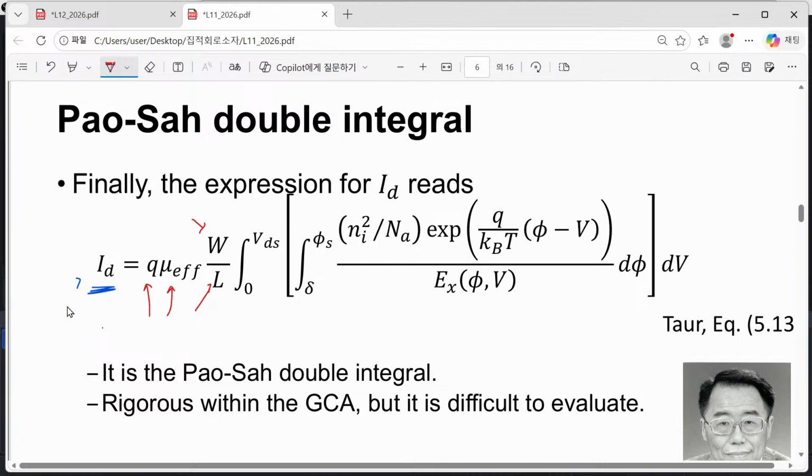You can draw your transistor's width, and you can draw your transistor's length, so it's okay. And VDS, this is the bias voltage you have applied to your drain, so this is your decision. And what else? This is delta. This is not exactly known, but this is quite close to 0, so it doesn't matter.